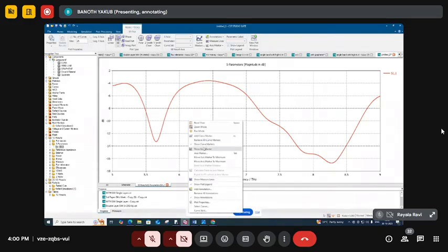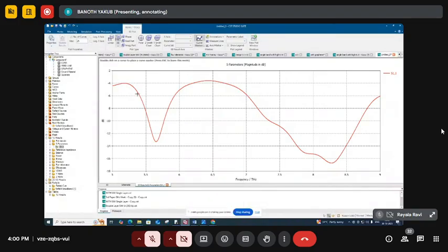You can see the tunability at the first band. The band is shifted to 5.53 and close to 5.7. The band is decreased here. At the second band, it is starting from 7.1, but it is shifted to 7.3. The last band is closing at 8.4, here coming to 8.6. So this is the tunability of that particular antenna's results.